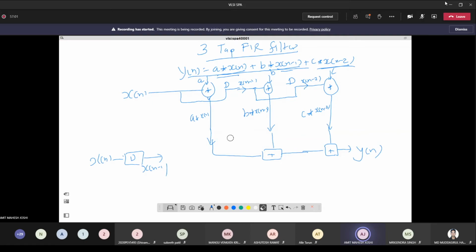Okay. So here ultimately for this I should know what is the delay. So what I believe is that for a multiplier it has taken 2. This is just a wild guess. Okay. So when you are implementing and you have designed one particular adder, you have designed one multiplier, then you know the delay. Just to explain you, I am taking multiplier as a 2-unit delay, adder is a 1-unit delay, and my assumption is also reasonably good enough, because always your multiplier would take a larger time than your adder.